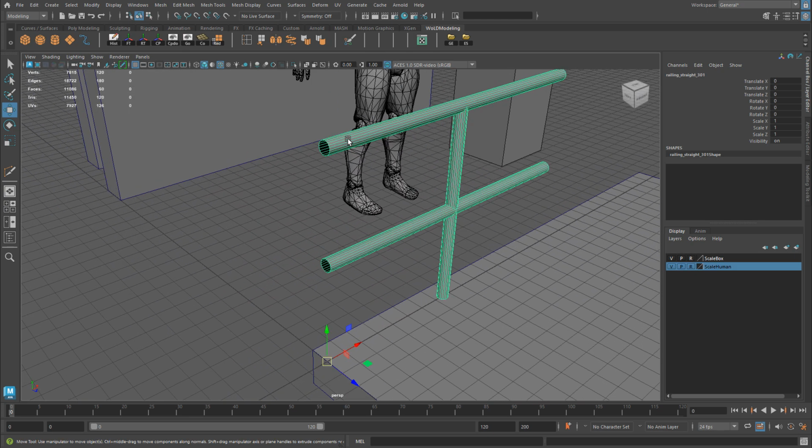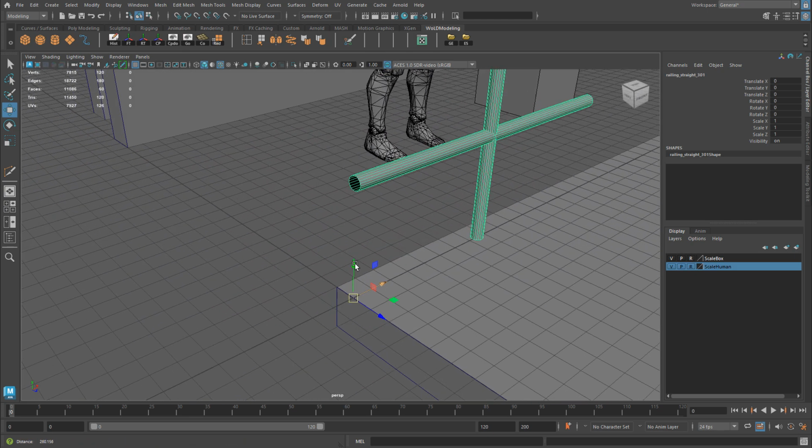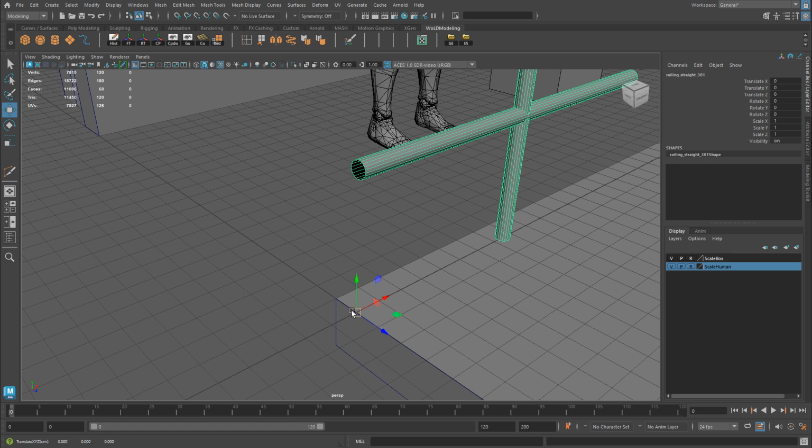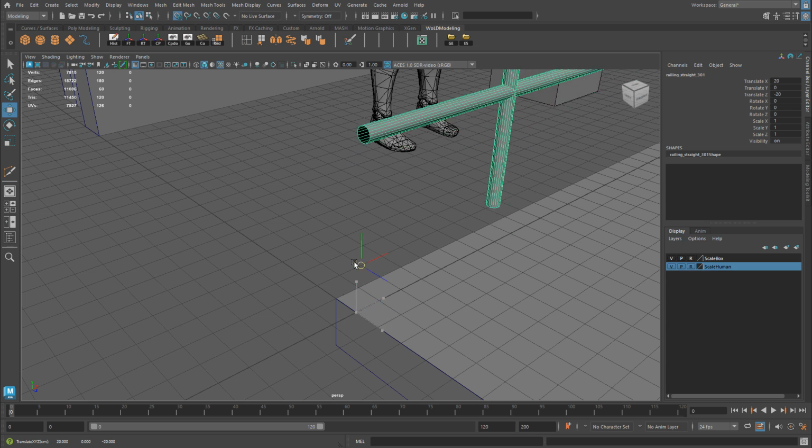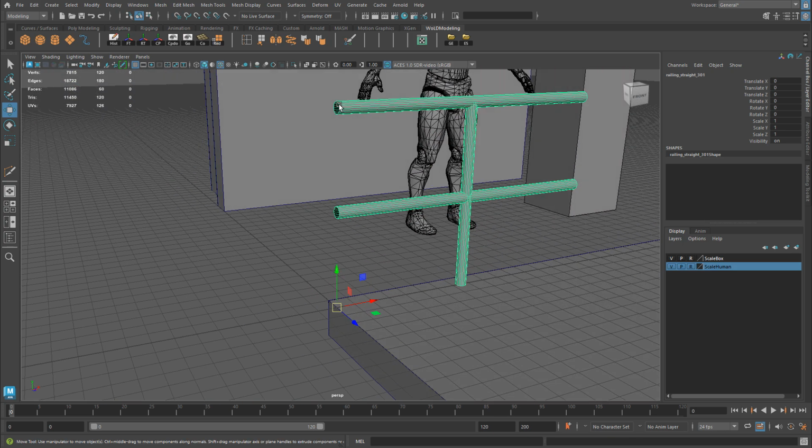And all I need to do is make sure that the mesh is snapped exactly where we were working on for the rest of the pieces. In this case, back in world origin, but it could be on any grid point really. And then I'm going to bridge these edges and these edges using a blend, so it's a curved geometry.